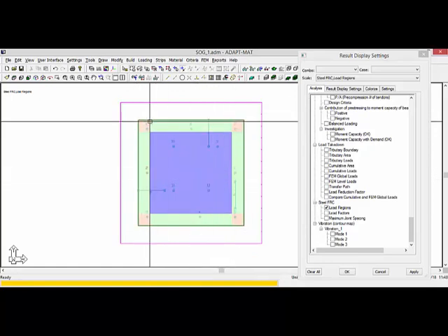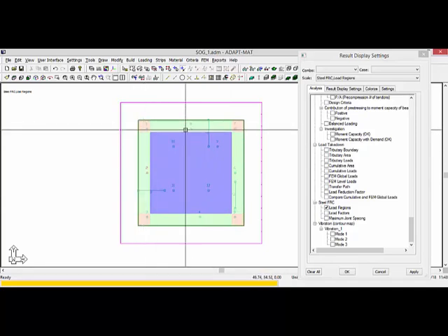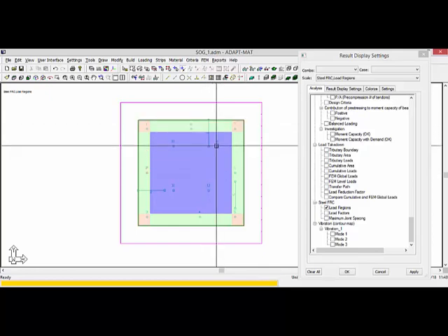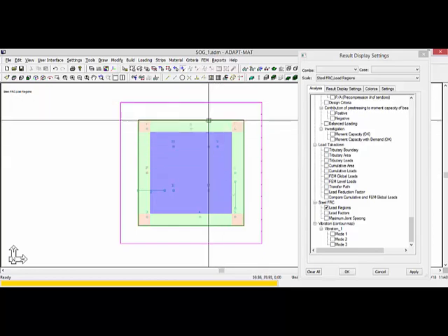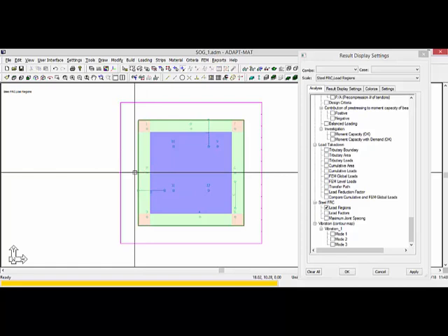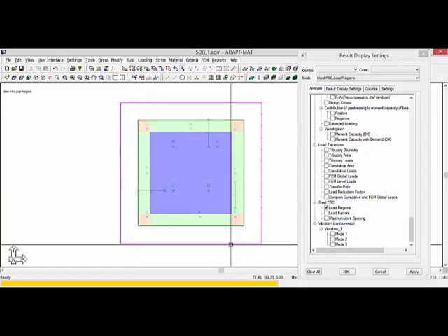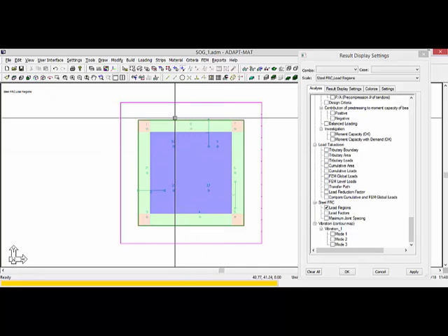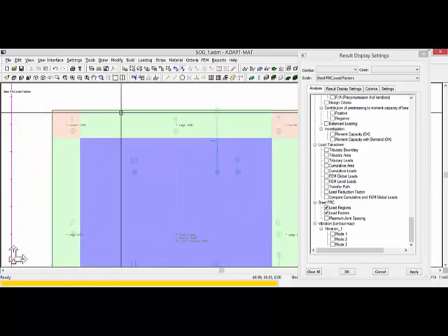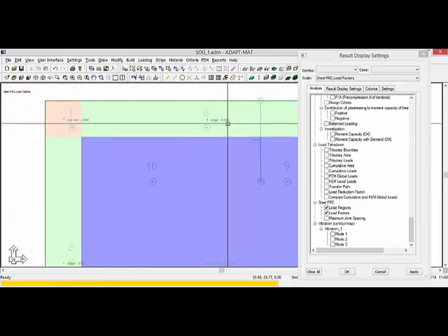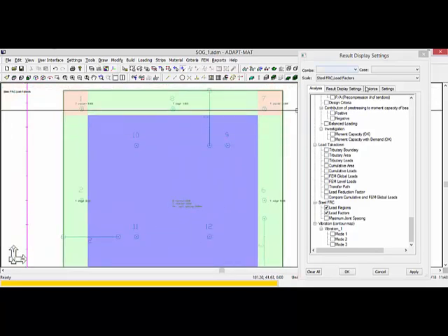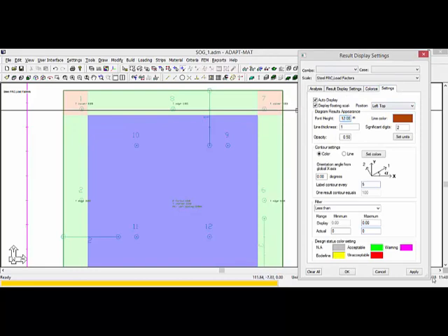So this indeed is a corner point load. This is an edge / interior line load. We're going to classify it as edge. The program can handle a line load that passes between 2 zones. This is an edge load number 2 that we classified. So we now have our zones considered, and if we look at the load factors, I'll just zoom in here, you can see that the values for T corner, T edge, and so on are currently set to 0. So I'll go ahead and just increase the font size for those zones